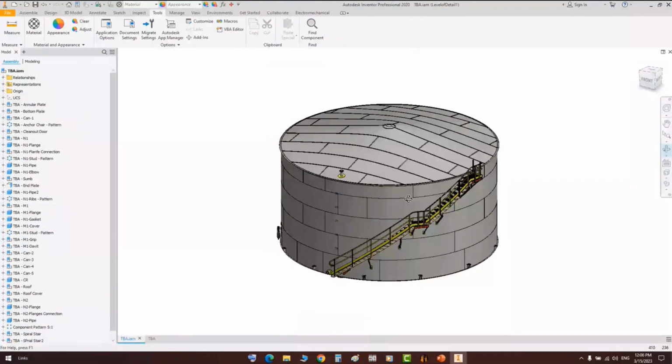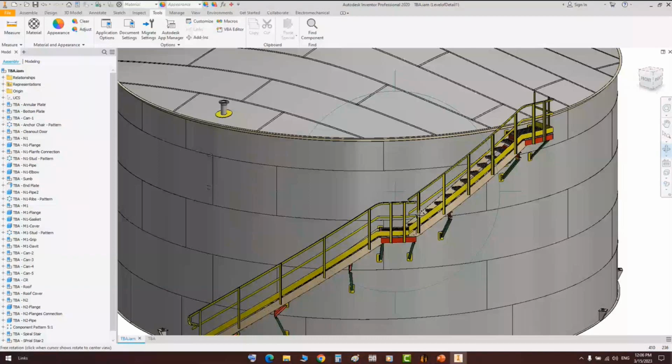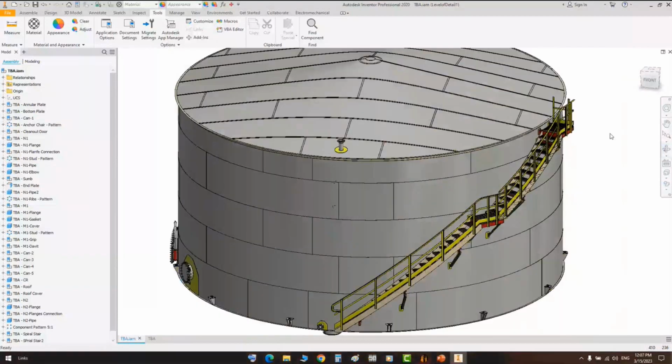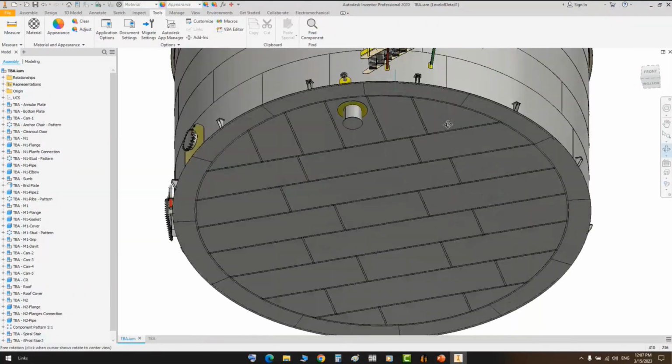Mr. Ahmed, related to the bottom plate, I have a few queries. In the bottom plate, as per API 650, we need to ensure that the distance between each 3-lap joint shall be 300 mm minimum. So is this check being done? I mean, does the software take care of it automatically, or do we need to check this manually?